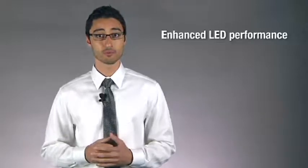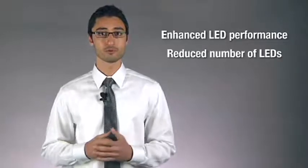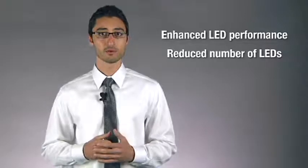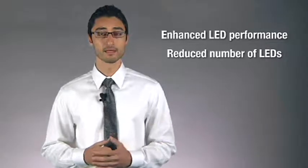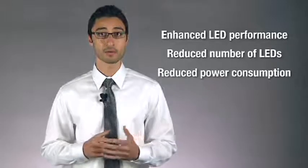The improved hot-cold factor is implemented in the Luxion Rebel illumination portfolio LEDs. So by simply designing in those LEDs in your lighting system, you immediately gain short and long-term benefits, like enhanced LED performance even when operating at higher junction temperatures, reduced number of LEDs needed to achieve a target light output in an application. In other words, you get more usable light, and reduced power consumption and overall system cost and payback period.